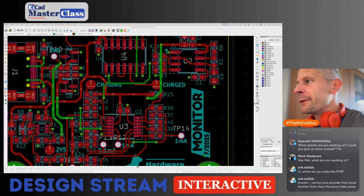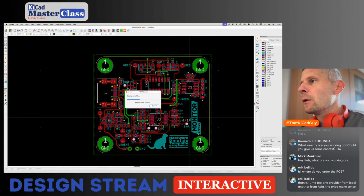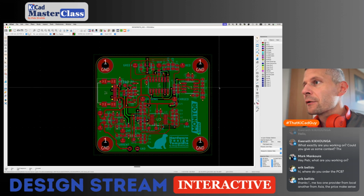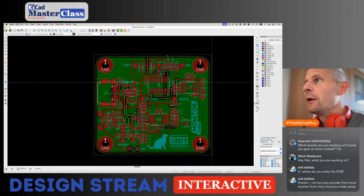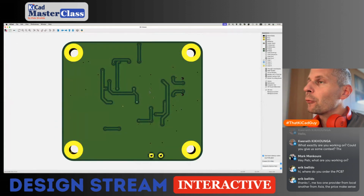So I'm back, and the PCB is almost ready. I used the two-sided PCB standard. This is a normal board. I used the bottom layer as the reference ground with a copper pour. The top side doesn't have the copper pour intentionally.